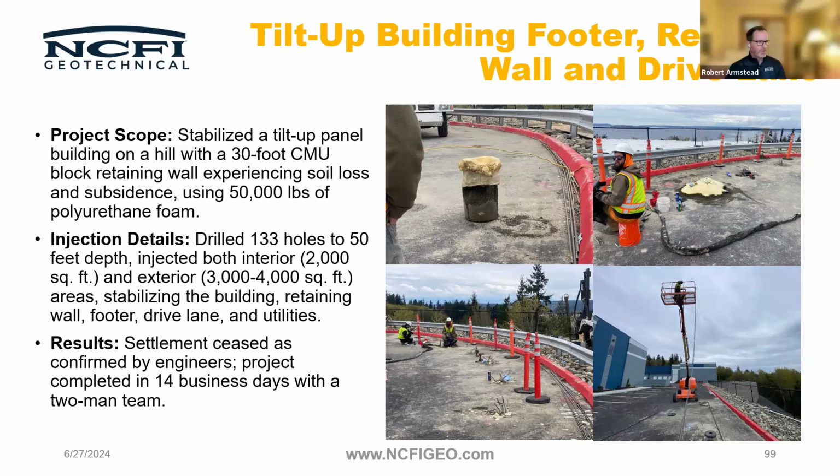What do you do with the tubes when done? Pull them or push them down? Typically, you're going to abandon them, but you should cut them even with the surface. A lot of contractors use a type of grout or something at the surface to help cover them up so they're not an aesthetic issue.